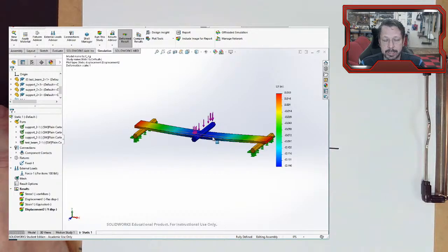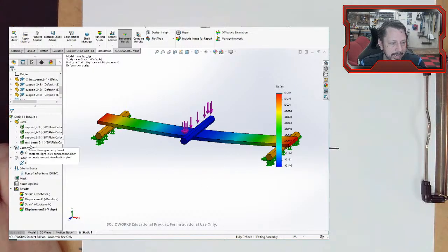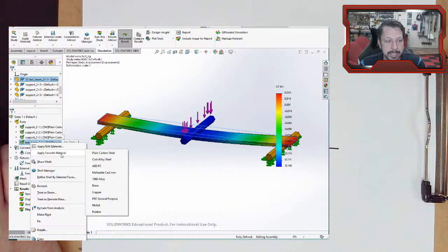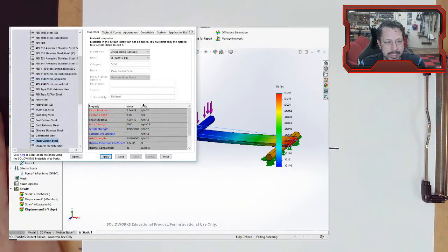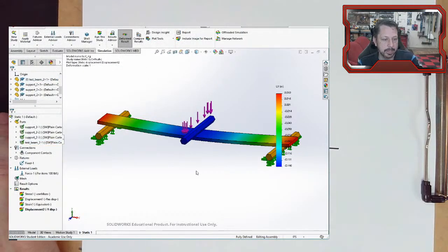You don't have to make everything out of steel. Maybe you make your support bars out of steel, but you could make your test beam out of aluminum or brass or copper, whatever material you want to do. Back out the modulus of elasticity like we did with the equation of the elastic curve for a simply supported beam with a point load in the middle of it, and see if you get numbers that are reasonable for those materials. You can even check with the actual material you assign, because it will tell you what the modulus of elasticity for that material is. It assumes it is 30 million, or 11 million for some kind of aluminum, whatever.